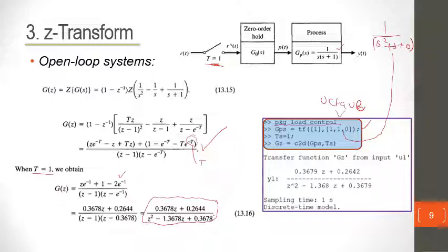The coefficients of this polynomial are: the first one is 1, the second one is 1, the third one is 0. So you have 1, 1, 0. On top, the polynomial just has a power of S of 0, which is 1. So the top polynomial here is that. You say your transfer function has numerator 1, denominator 1, 1, 0, and sampling time 1, and then you simply create your transfer function. That becomes your transfer function.